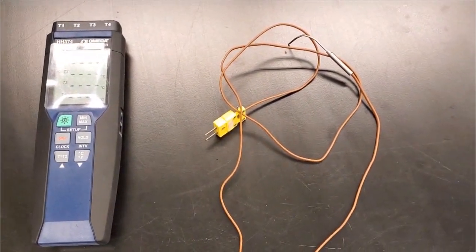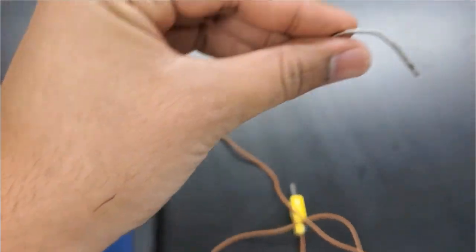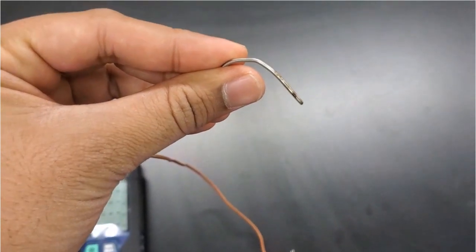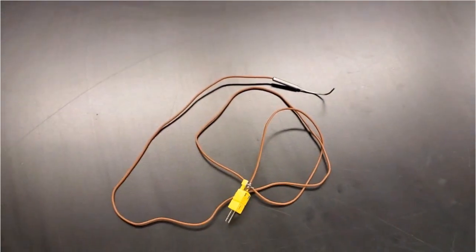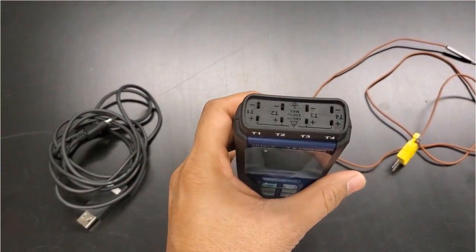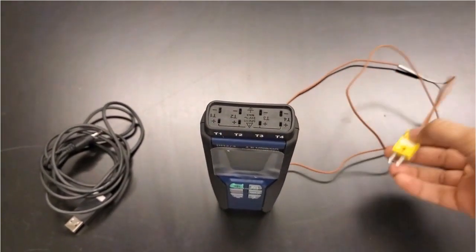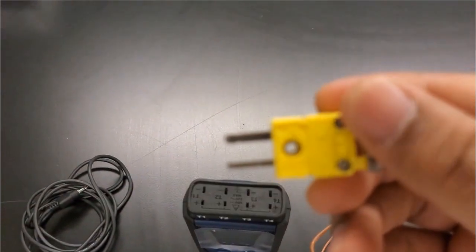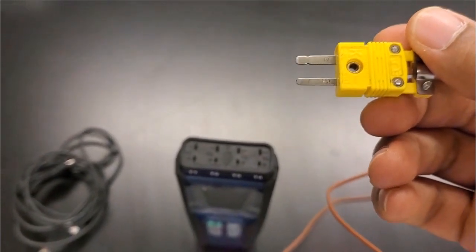And what you see to the right is the K-type thermocouple, which allows us to go as high as about 800 degrees Celsius, or even higher than that. And that's the tip of the thermocouple that we have, which is kept at the location where we want to have the temperature measured, right? So this thermocouple is plugged into the 4 different channels that we have here to get the values that we need.